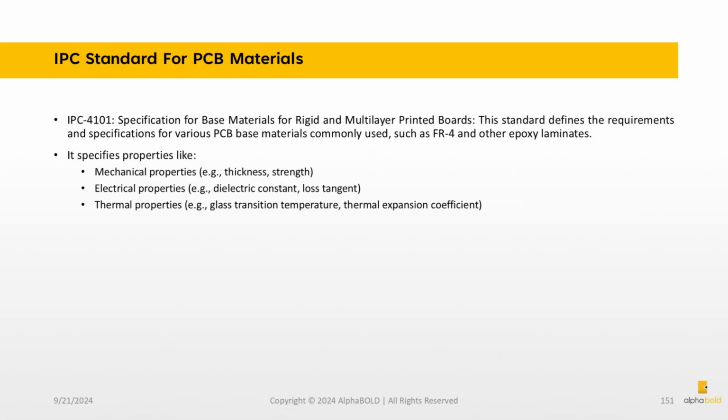This standard defines the requirements and specifications for various PCB base materials commonly used, such as FR4 and other epoxy laminates. It specifies properties like mechanical properties, e.g., thickness, strength; electrical properties, e.g., dielectric constant, loss tangent; thermal properties, e.g., glass transition temperature, thermal expansion coefficient.